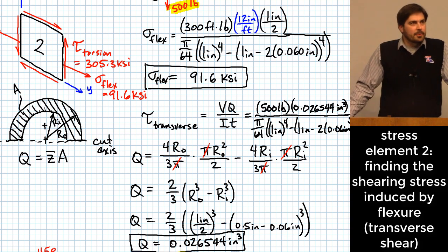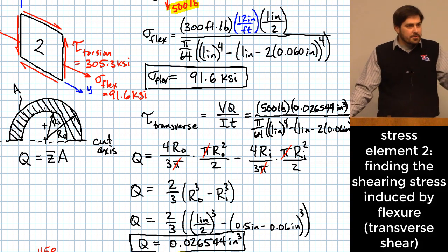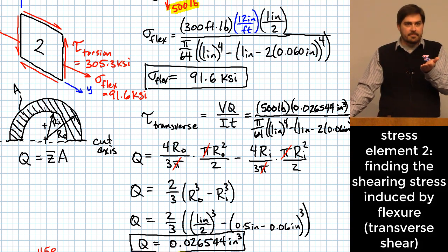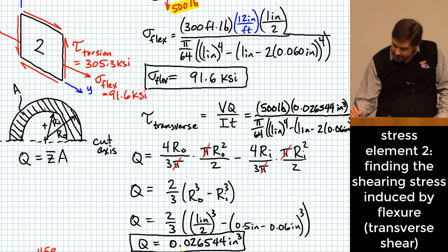Okay. Anyone here remember what T was? Thickness, okay. Thickness of what? Okay. It's related to wall thickness. Someone says wall thickness. It's definitely related to wall thickness. Okay. It's a little bit trickier than that, though. Not much, just a little bit. What T refers to in this formula is the amount of thickness that you would have to cut through to make the cut that you just made. Right? How much material did you have to cut through in order to make this cut? Right? So it's not just one T.